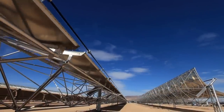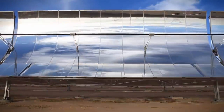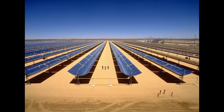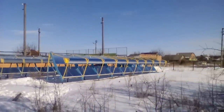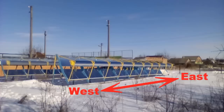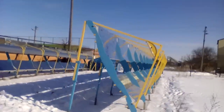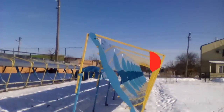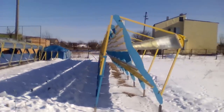Now I remind you that those expensive solar heaters must constantly turn according to the movement of the sun across the sky, and usually they are placed perpendicular to this east-west line. Unlike them, the solar heaters of my solar station are parallel to this east-west line. That is why their mirrors may not turn during the day, because solar radiation from my motionless mirrors enters this receiver for most of the day, except perhaps in the morning and evening.